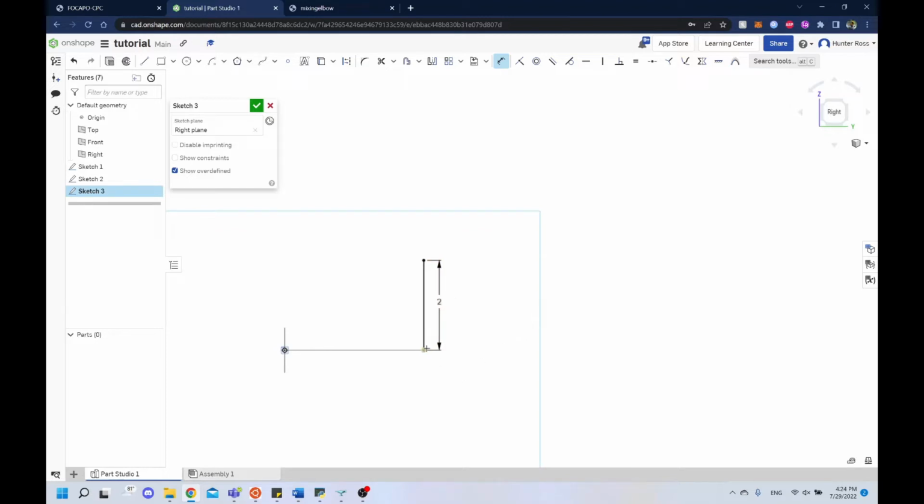This is the radius of our circle. And then we could start from here and make it a center point circle. And that would be one way to do it. But I think what would be even cleaner is if we use an arc, a center point arc. So we define where the center of the arc is and then sweep it along a path. But for that, we'd need 3 points. So let's make another line. Press escape to get out of that. Press D, 2 meters. We have another one.